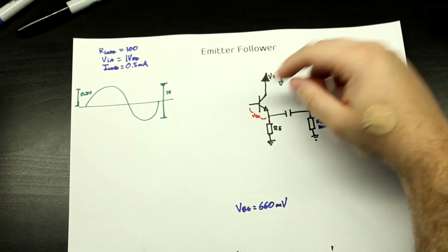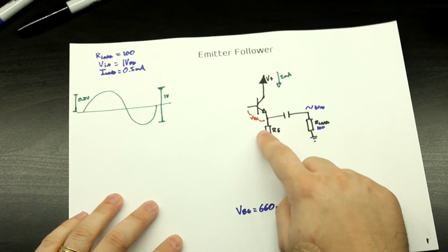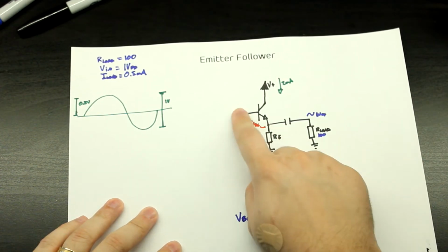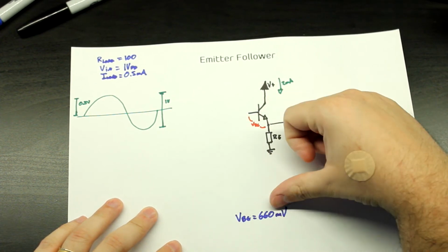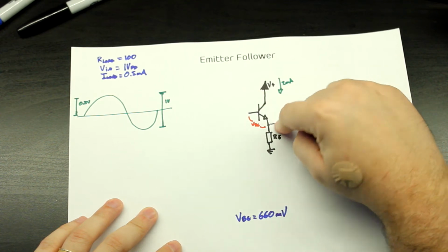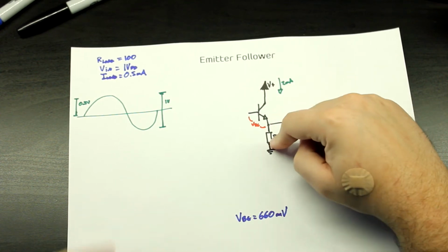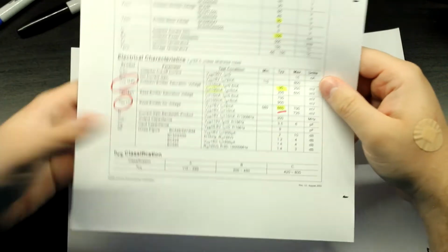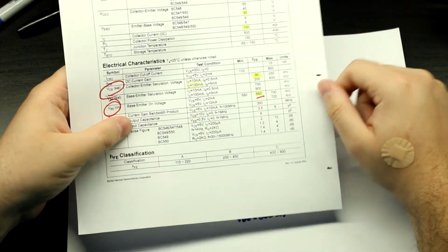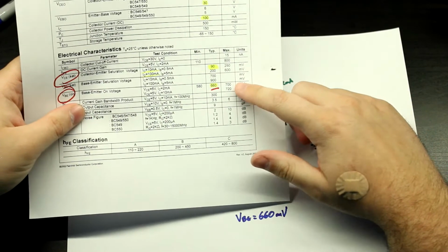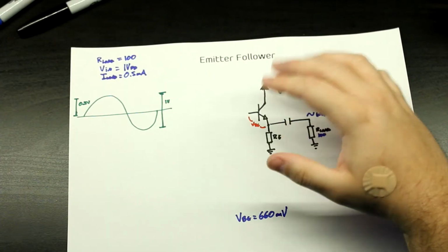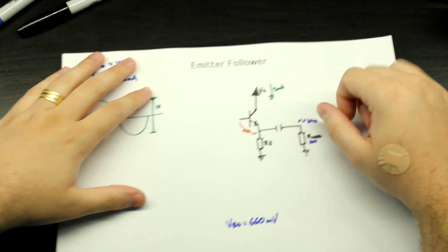And this is going to determine the lowest voltage that we can have here in the base of the device, because we need to have at least VBE here to get this device to conduct. Of course, there are variations in VBE, so you always need to put a voltage here that is above VBE, just so that you can take care of all those variations.